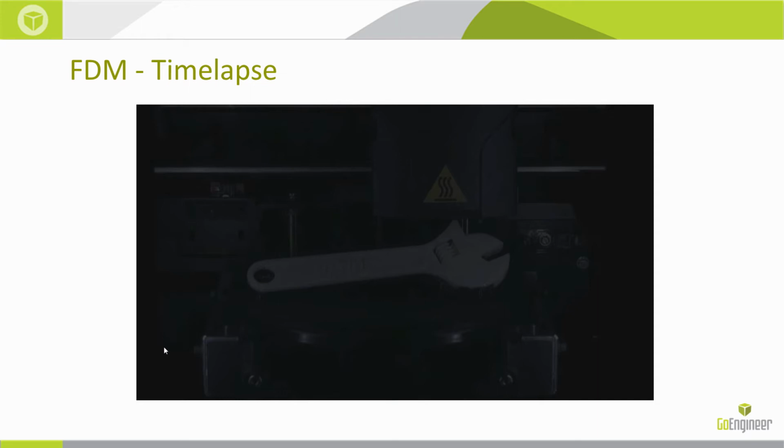That negative space is filled with the support material. The support material is sacrificial, meaning once we take this print out of the machine, we're going to remove the support material. In most cases, that support material is actually water soluble. So I would take this wrench, I would throw it in our heated bath, and I'd come back in a couple hours and I'd have a working wrench. Okay, notice we've got 2 parts here that are really meant to move in relation to each other. That's how these crescent wrenches work, right? We spin that little thumb screw and it opens or closes.